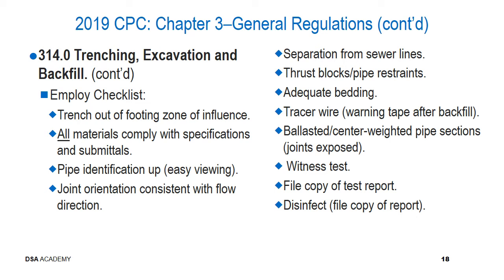As we just discussed, you want to verify that all materials comply with the specifications and the approved submittals. You want to make sure for your ease, and I would encourage all project inspectors to do this as soon as possible, so that the contractors performing this work become trained to a certain extent.